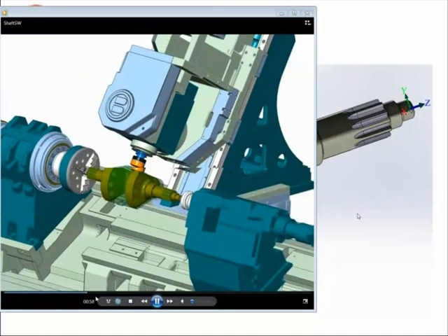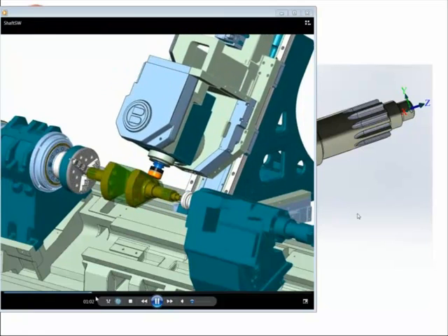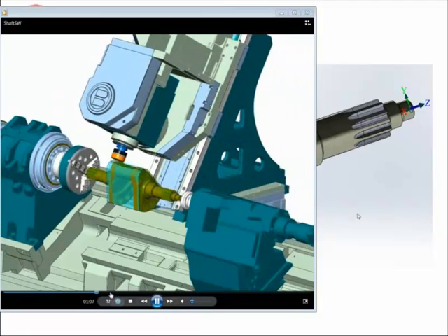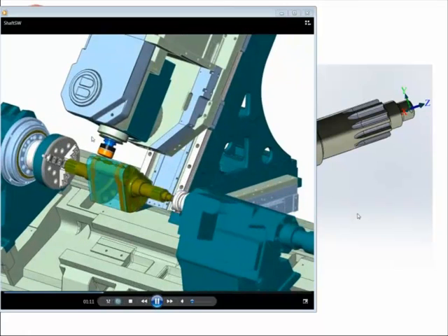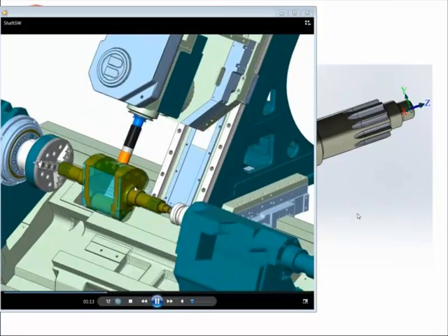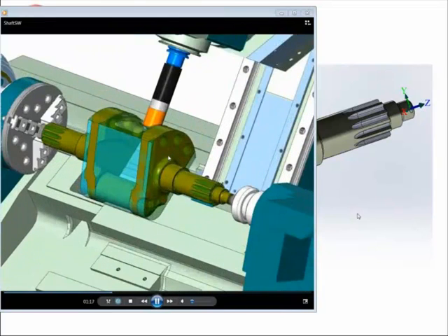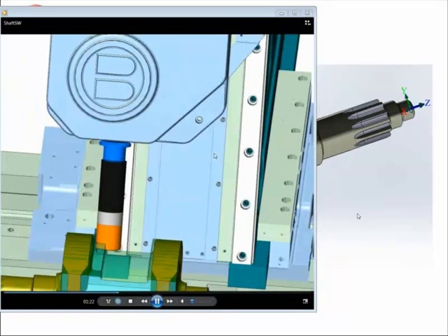Actually, this particular toolpath is using stock recognition. And once this roughing is done, we'll come in with a different tool, and we will have to cut this cylinder here, just this cylinder, which is eccentric, with this tool. And my actual toolpath is a zigzag toolpath that starts in the center and steps out, zigzagging, maintaining climb cutting.